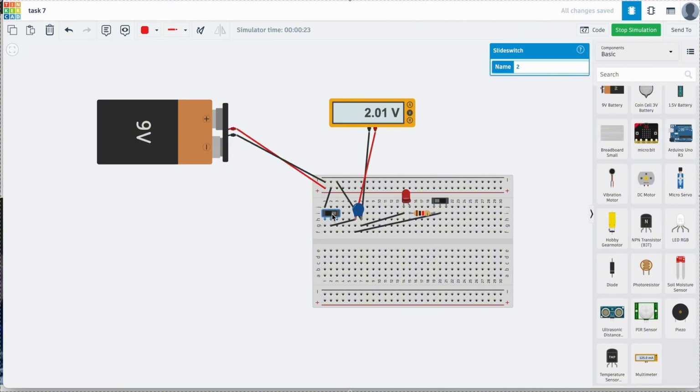So it is discharging, and you can see that it discharges pretty fast at the beginning, and then it goes really slow. So your LED is going to stay dim for a really long time because now it's going really slow. You can tell it's going in the hundredths, taking a while to discharge. So if I wanted to, I could just turn the LED off, and it would no longer be getting charged from my capacitor, but you can see that my capacitor is now stopping at 1.53 volts. Since there's nothing to supply that voltage to, it keeps that charge right there.